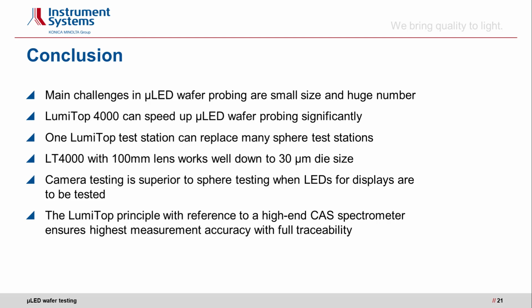Just one comment here: the Lumitop 4000 with our standard 100mm lens works well down to 30 micrometer die size. Camera testing is always superior to sphere testing when you are testing LEDs for displays. And the Lumitop principle with the reference to a high-end spectroradiometer ensures the highest measurement accuracy with full traceability to national labs.